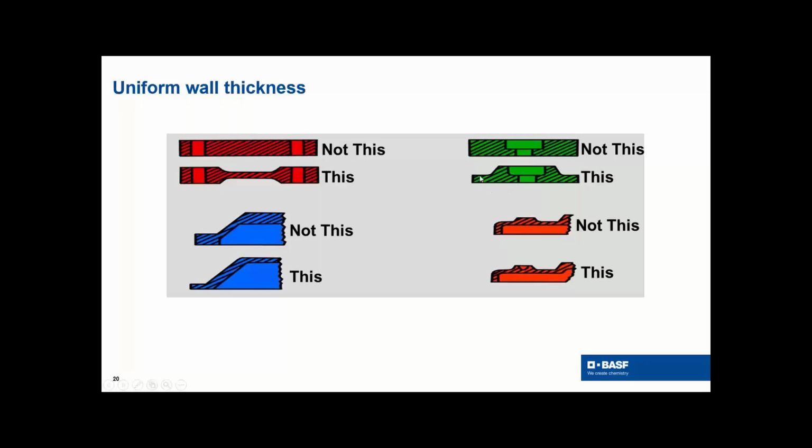Basically, if you can get more of a uniform wall, like this part has been redesigned, now this wall and this wall are about the same, and I'd even design it a little bit further. I would put a little bit of a divot in here to make it all uniform. And this will give you a low stress material and minimal warpage.